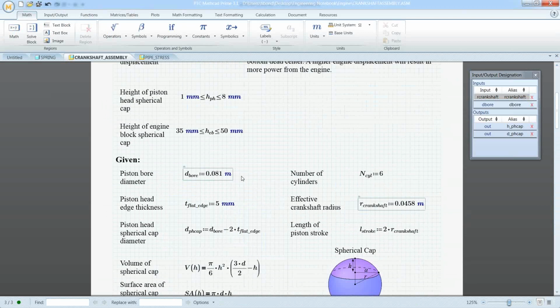So you saw that. Where was it? Up here. Even though when I took the measurement, the template of the Creo part is in millimeters, when I pull it back, it's going to come back to the default Mathcad unit system of meters. If I were to switch that to the US system and redo that, that would have come back in feet. But the conversion's done correctly for you.